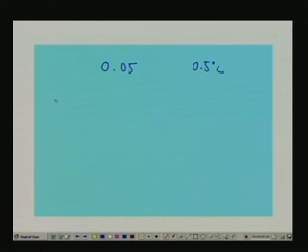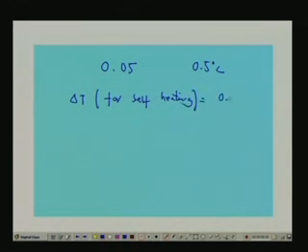Now, the error may be introduced due to self-heating of the RTD. To ensure that this is not so, we choose the temperature change due to self-heating to be 10% of the given resolution. So, we have taken the delta T for self-heating equal to 0.05 degree centigrade.